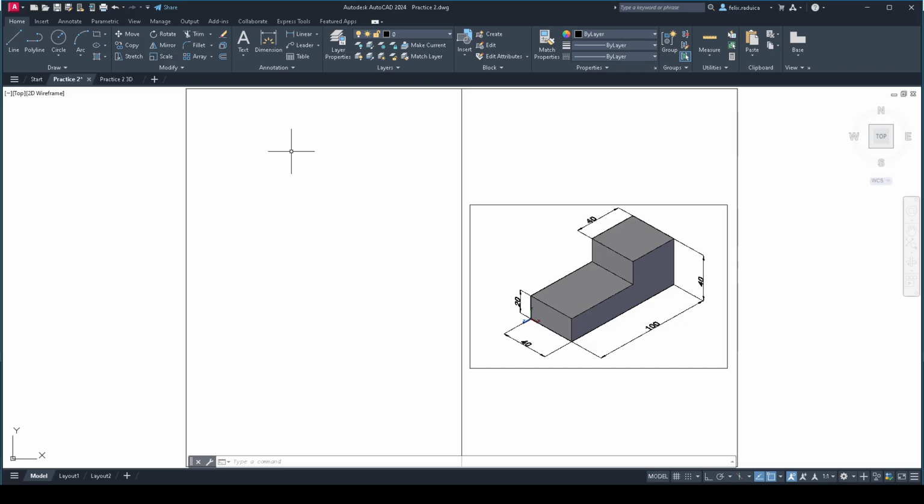I want to draw my first rectangle here, which will be the front view, the projection of the front of the part. And to do that, I will use A as my X coordinate, and Y will be all of the height here minus B. So that will mean that we'll have a Y of 227. So give the rectangle command, then give the coordinates 25 and 227.